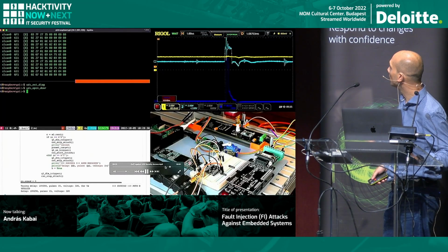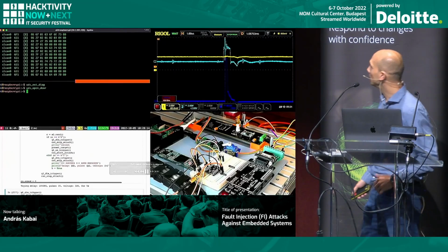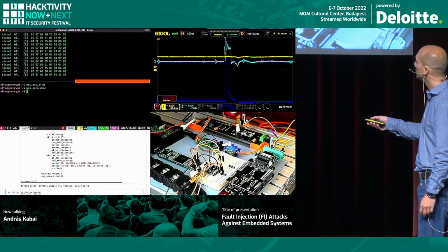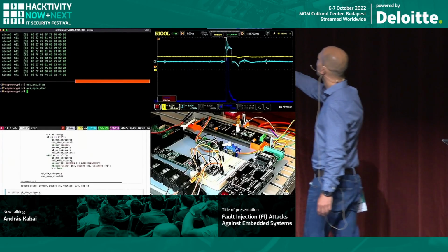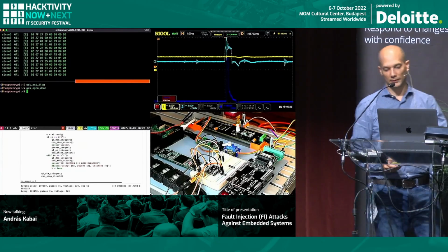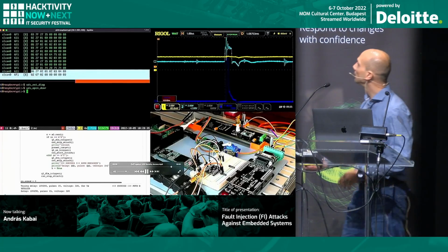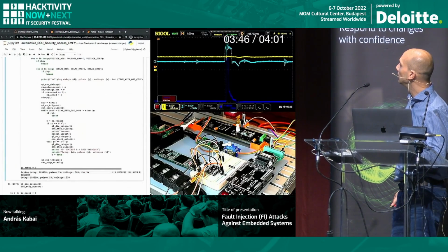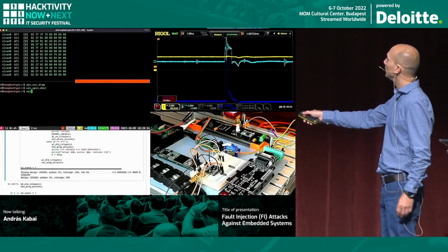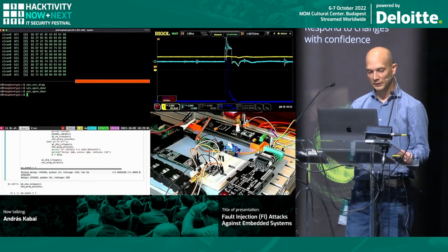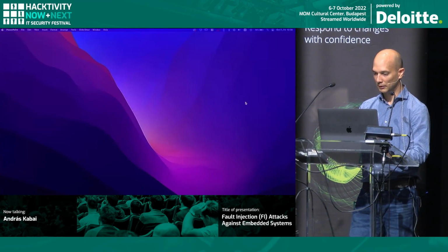And finding the sweet spot is just happening here. Where basically the appropriate settings and the magnetic pulse targeted and released against the microcontroller let us be authenticated. As you can see, we get a positive response there. And having this access, we can easily jump back here and execute the same command, which opens the doors for us. So this way, we managed to bypass the authentication on the Unified Diagnostic Service.